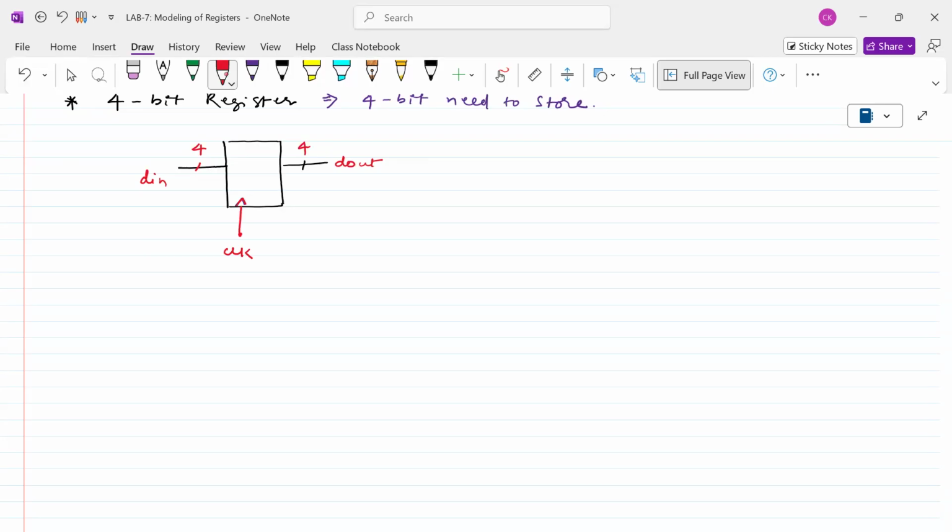Next, of course, we would like to have one important global signal that is called the reset signal, RST. We always prefer to use asynchronous reset. That means first you have to clear the contents of all the registers, and then apply the clock and get the output, transparent or stored.